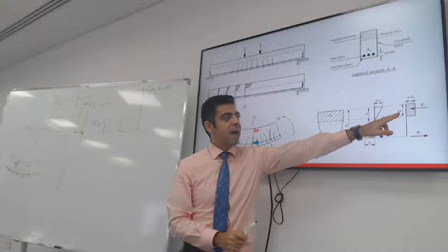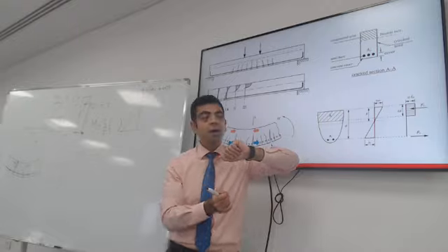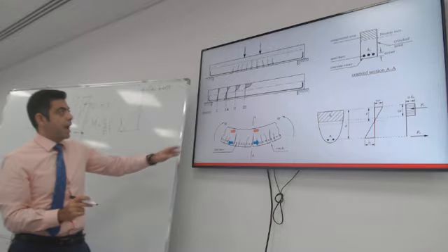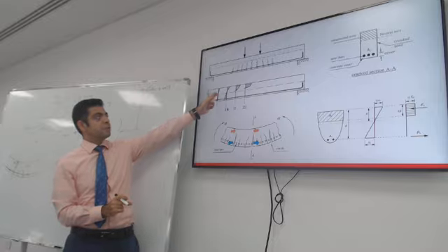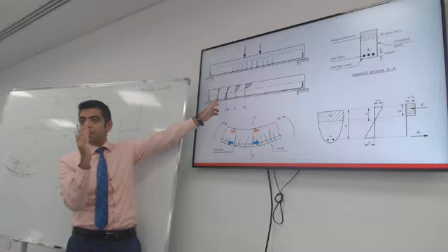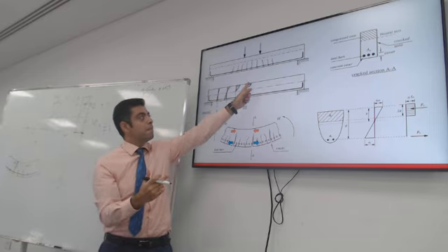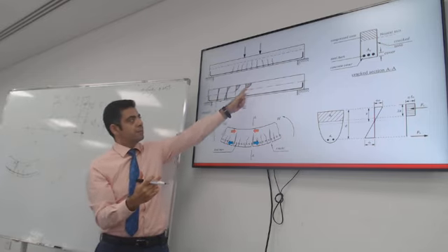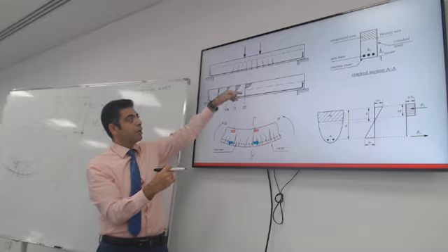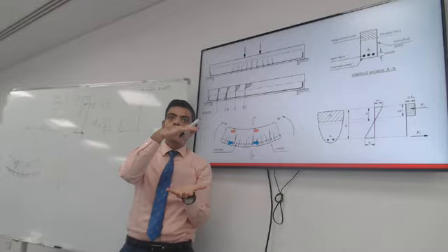This is the idealized shape of forces on the section. Rather than looking at the stress distribution, linear in the first part, then as you exceed the stresses, the shape of the stress block on the concrete will start to look like the compression curve for concrete.